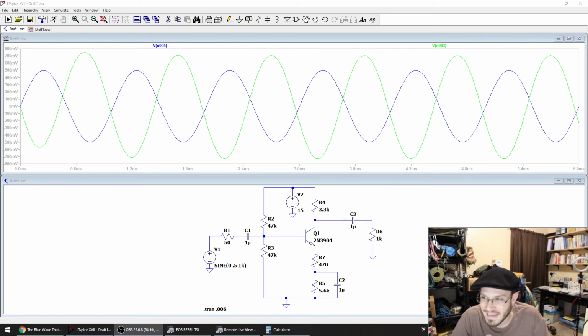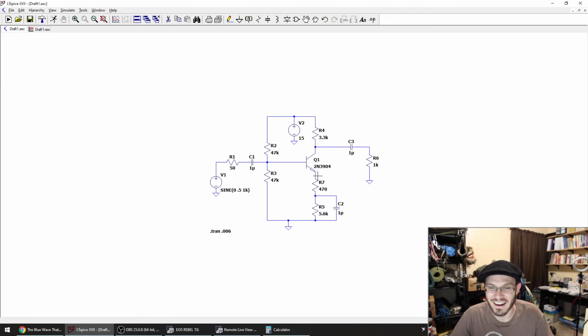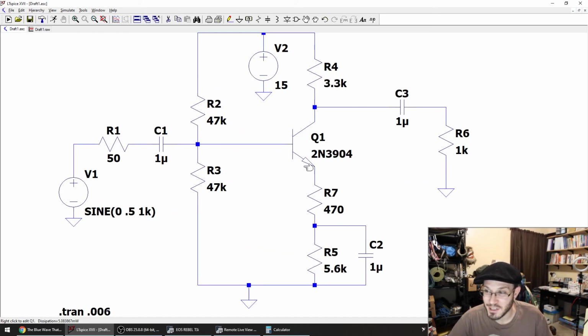Okay, so anytime you attach two wires together, I don't care where those two wires are, even in this circuit, even here, any two things that you attach to each other has an impedance. It's just sometimes we don't have to pay attention to it, and sometimes we do. In the case of the source driving the input to the amplifier, we have to pay attention to it. In the case of the output of the amplifier driving something, we have to.